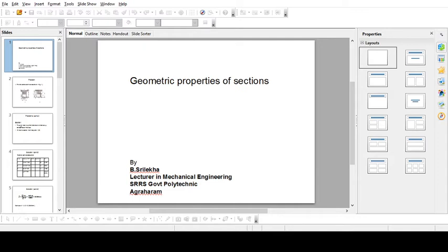That will give you minus 6084. Next, the area is 50 into 8, the topmost section. It is 400, and y is equal to 44. So A into y is 44 into 400, which is simply 17,600. Now you can write the sum of the areas as A1 minus A2 plus A3. So 1360 minus 468 plus 400 is equal to 1292.